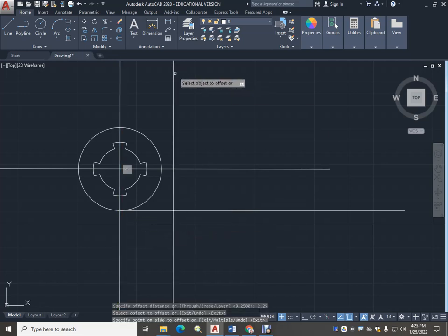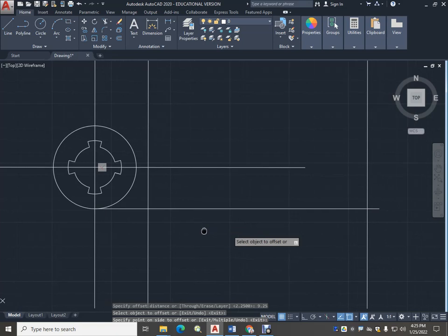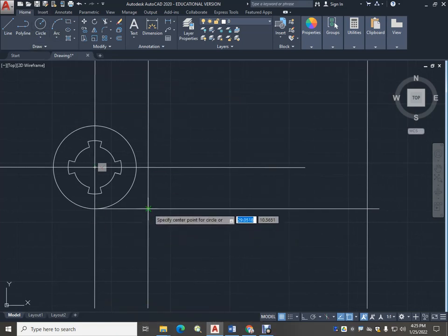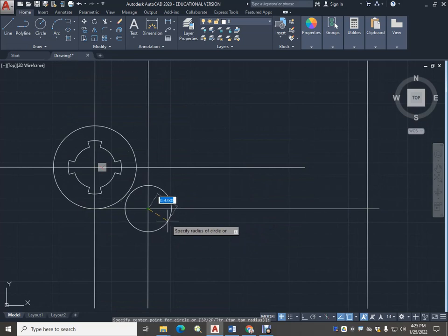Put that one there. And the next one is 9.25, but it doesn't go back to the center. It's in addition to this one. So we have the 2 centers out here. Each of those gets 2 circles, 1 radius and 1 diameter. Radius 0.75.